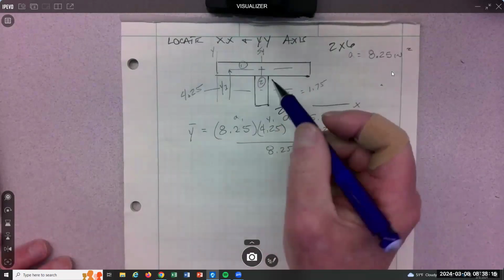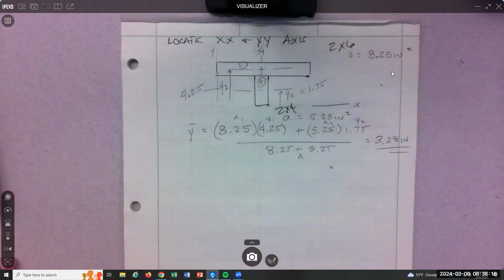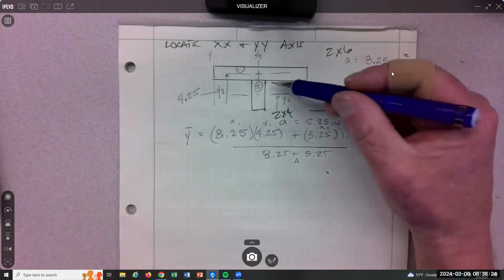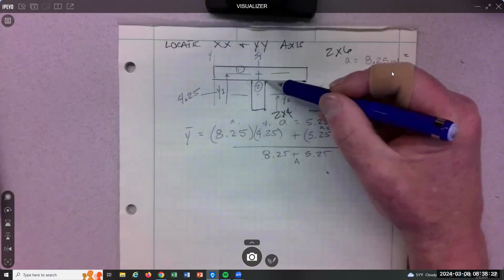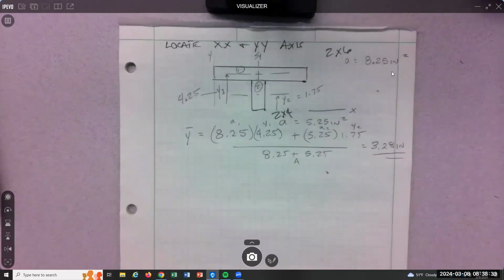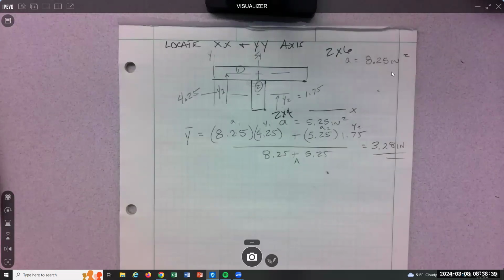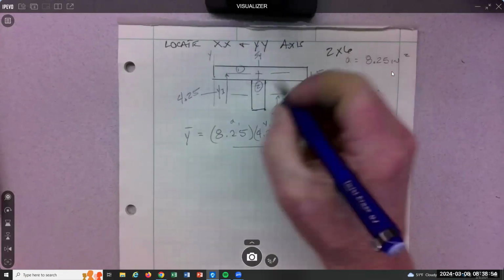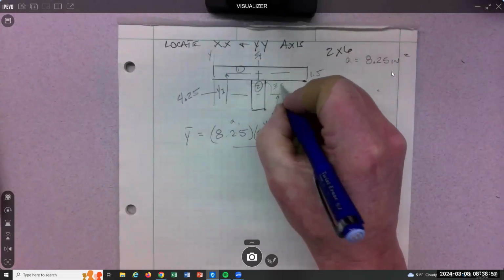Because we don't want a lot of bending stress in this connection, whatever this connection is, probably nails. So contractor's gonna nail it up. Right, and if we get that neutral axis close to this connection, there's no bending at the neutral axis. That's where it goes from compression to tension when you bend this shape. So. Yeah. Questions? Yeah, this is 1.5. This distance here is 3.5.